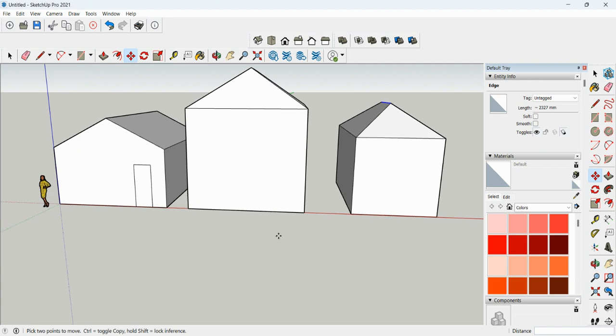Okay, again for the door, let's draw a rectangle. Put it here. Make sure that you are on the edge. Can everybody follow? And then just lift it up like that, and let's put the value. Let's say this is a bigger door. I make this 1200 by 2400. So it's a bigger door. So there's the bigger door.